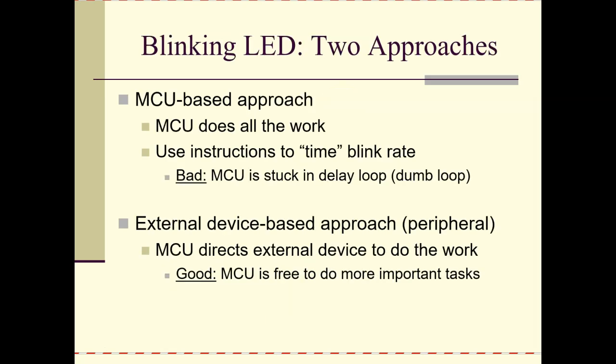There are two approaches to doing anything in digital land with a microcontroller in your system. You can have the microcontroller do the work, which means executing instructions, or you can offload that task to some external module. The timer counter that we're going to talk about in this experiment is an external module that gives the processor freedom to do other things rather than something as mundane as counting and timing things. And you'll see that come up a little bit later.